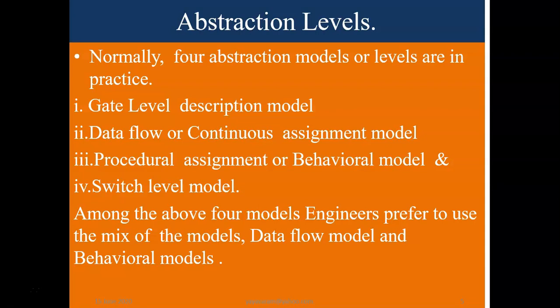But generally, there is a common understanding that the switch level model is considered the lowest abstraction level model, where they use switches like MOSFETs or FETs. And the gate level model description is the next level. That is, it is also a low level model. In this class, we will concentrate mainly on the gate level model. We will understand clearly why it is called gate level model, what is its importance, how to write a Verilog code in gate level model, etc.